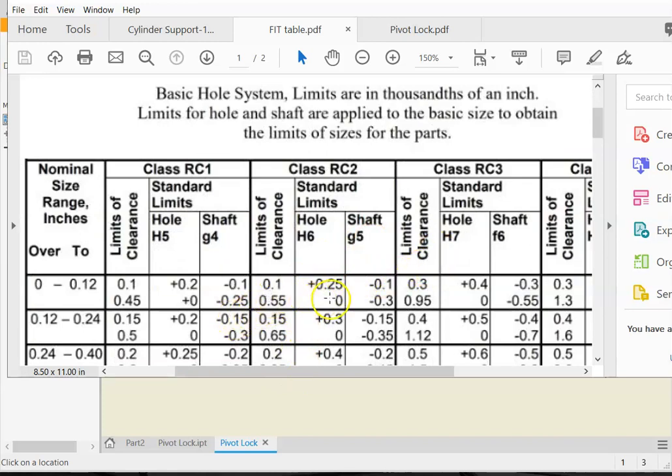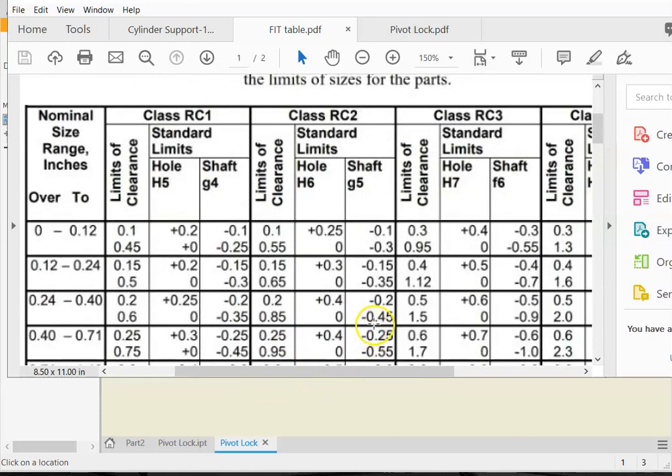So here, for example, you see the 0.25. Of course, tolerance cannot be 0.25 for this small hole. So it has to be divided by 1,000. So you would move 3 zeros to the left. So that's how you would do these. Okay, so they give you information in your textbook regarding this hole for 0.5 using the RC2, for diameter 1 basic hole system using RC5.